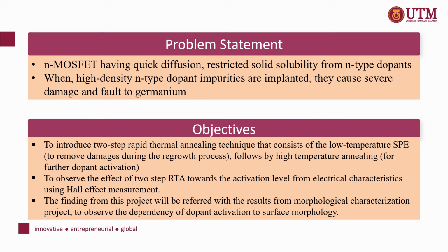The problem statement of this project is that N-MOSFET has quick diffusion and restricted solid solubility from N-type dopants. When high density N-type dopant impurities are implanted, they cause severe damage and faults to germanium.